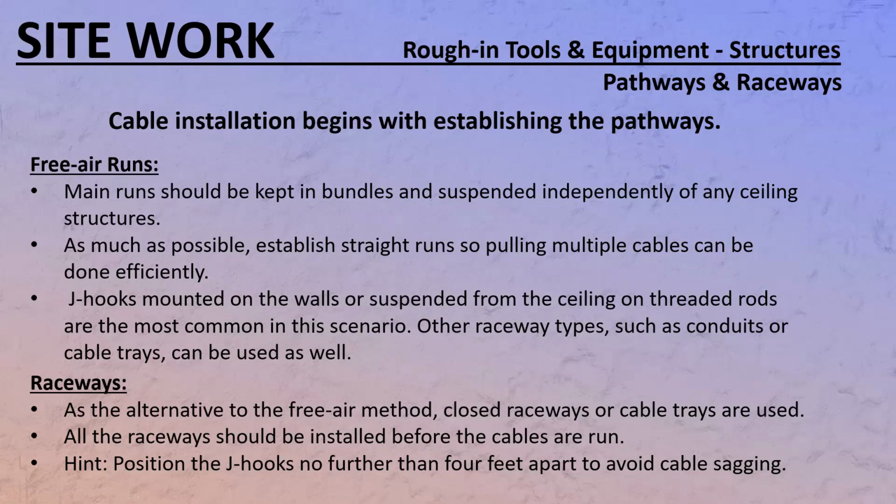So establish the straight run and use it to go as far as possible before the wires start fanning out into the individual locations. This way you can do the wires nicely, efficiently, and safely, and you're not going to run the wires all over the ceiling space. The professionalism of the installation would also be kept. Plus, if you need to get at any of the wires, you know where they are.